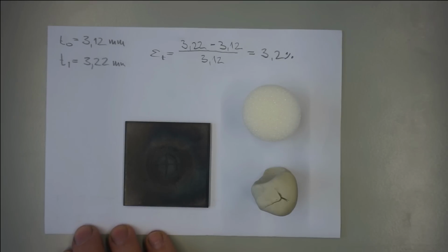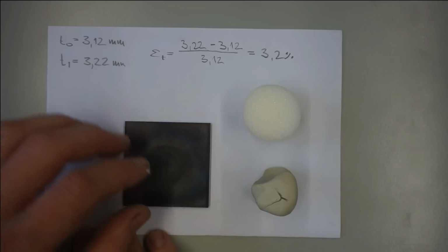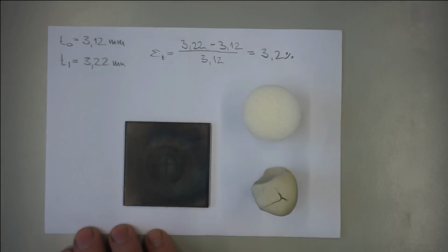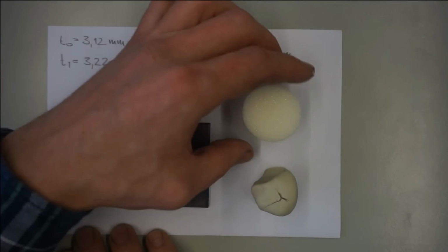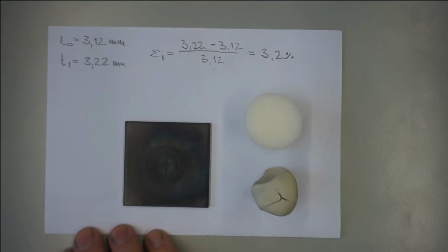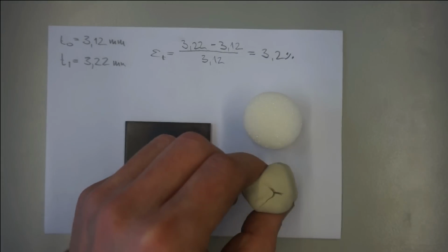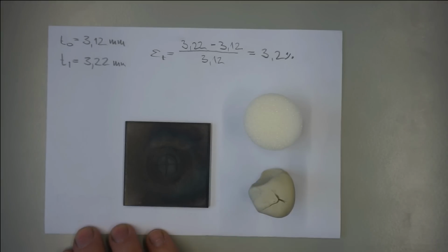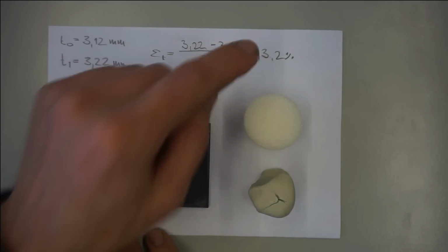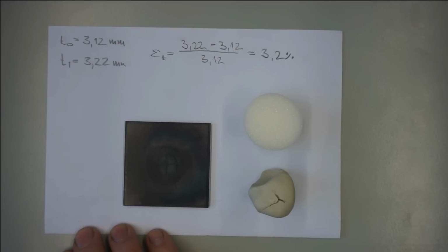We may answer this problem with the aid of the thickness strain which we computed earlier. What we know from ductile metals in general is that they can take somewhere between 0.1% and 1% of elastic strain until they start to deform plastically, like the putty. With our thickness strain being 3.2%, consequently we know that the major part of the deformation here is plastic. There is surely some elastic deformation due to residual stresses present too, but this is most likely only a little part of the thickening.